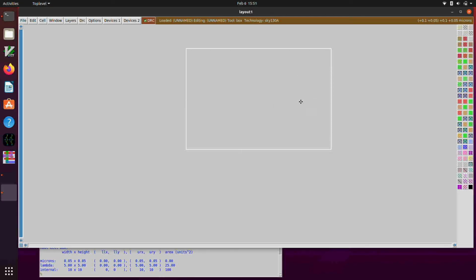Okay, so that's going to be much more useful for counting off, three times the 0.05 gives us a minimum length transistor and minimum width poly and that kind of stuff. So that's going to be a much more useful grid to work with. Now the other thing is there's different sets of design rules that can be enabled at a given time, and I'll explain a little bit later why that's useful. But for drawing a cell, we'd like to enable the full design rule set. So I'm going to go :drc style, drc paren full end paren. So this turns on checking all design rules.